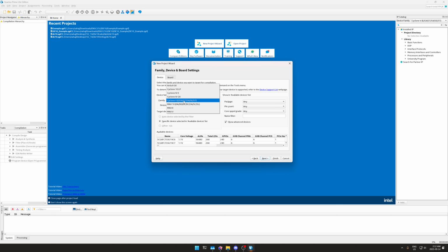In either case, you'd want to make sure you have the support package or reinstall Quartus with the support package. Let's go ahead and also add the device name. The DE-10 standard comes with this specific FPGA device, so I'm going to paste that in. It'll also be down in the description. So go ahead and select it, then click next.